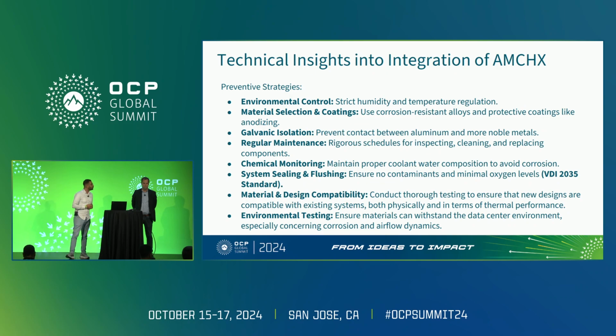So today, with the expertise of Valeo in the radiator and the heat exchanger, they developed a technology to galvanize this heat exchanger and have a more robust aluminum material, and to control the IT room environment by taking a safety coefficient for the temperature and the relative humidity, and also by testing this heat exchanger in the cold aisle inside our data center.